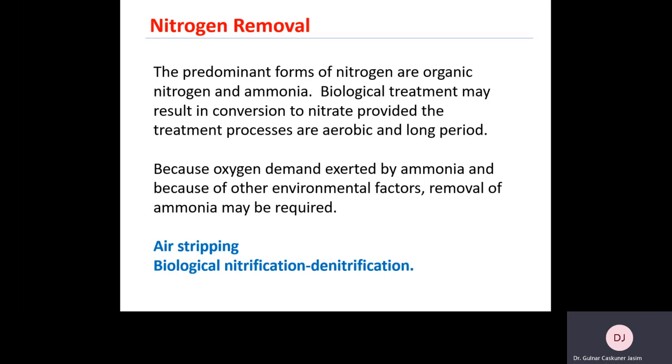The predominant forms of nitrogen are organic nitrogen and ammonia in the sewage, and biological treatment may result in conversion to nitrite, provided the treatment processes are aerobic and long periods. So this is another thing. Detention time should be long enough to allow these nitrogen compounds to be oxidized to nitrite and nitrate.